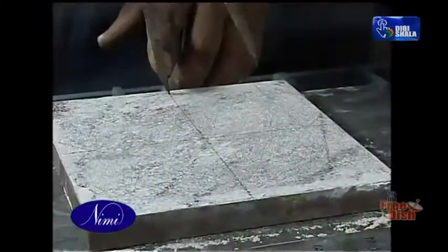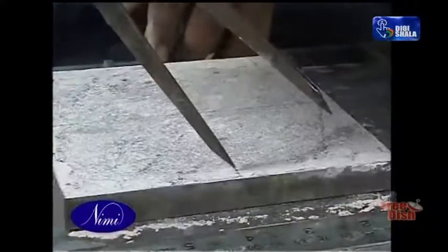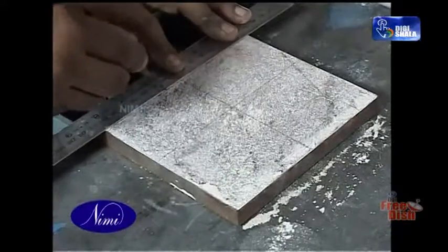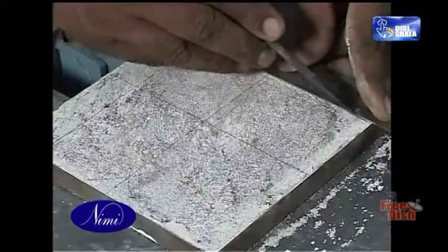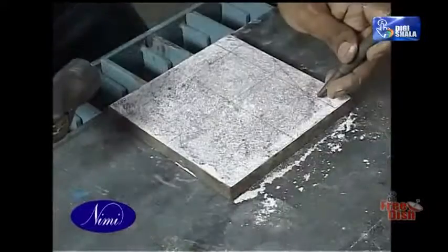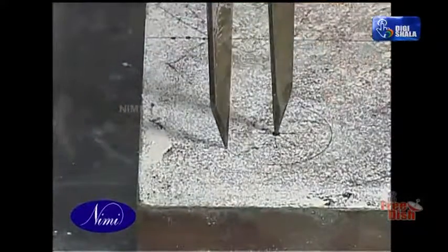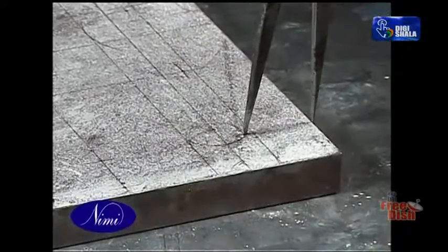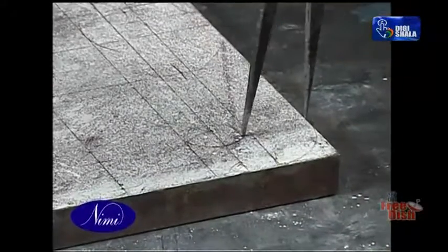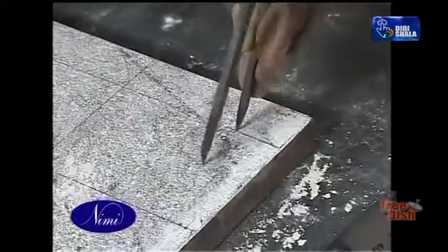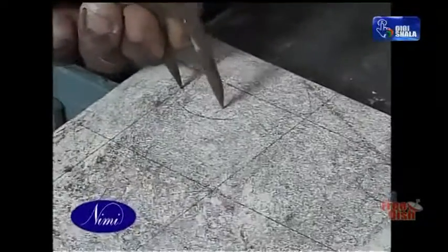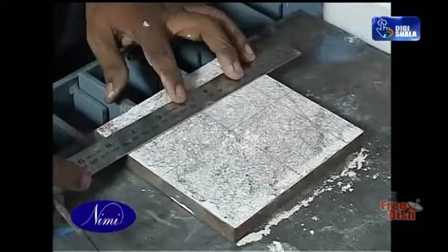Keeping the cutting allowance as 1.5 mm for a 16 mm thick plate, we need to mark the right angle slot to a size of 107 mm by 22 mm, a circular hole of radius 27 mm and a corner radius of 23.5 mm. Now, we need to mark the width for the right angle slot. Then, locate the center line of the slot.